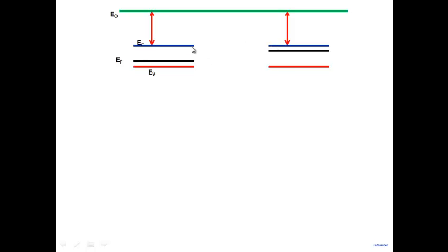Electrons will start to go towards this particular side. So this is from the band perspective. Earlier, I was simply showing you, from diffusion and all that, drift diffusion, what was happening. So this is from a band perspective. We know Fermi energy is higher. Electrons will move from higher Fermi energy to lower Fermi energy. And as they move, this region will become positively charged. This region will become negatively charged.